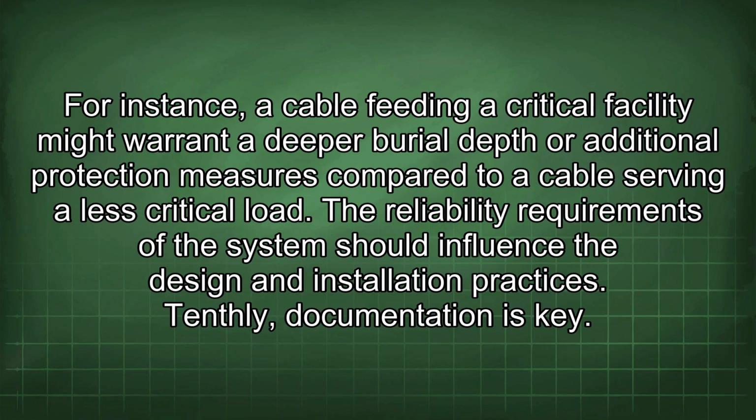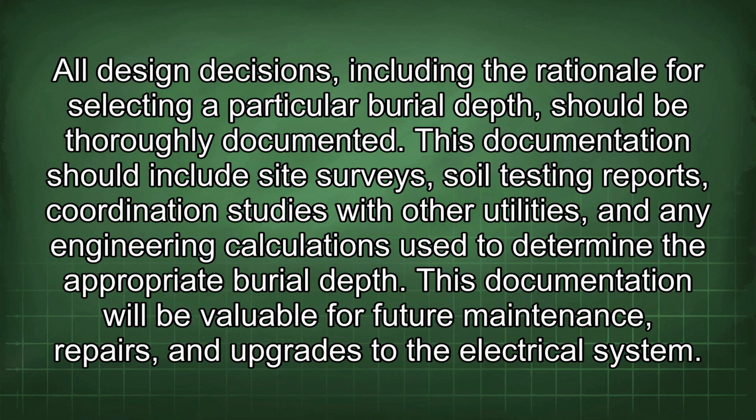Tenthly, documentation is key. All design decisions, including the rationale for selecting a particular burial depth, should be thoroughly documented. This documentation should include site surveys, soil testing reports, coordination studies with other utilities, and any engineering calculations used to determine the appropriate burial depth. This documentation will be valuable for future maintenance, repairs, and upgrades to the electrical system.